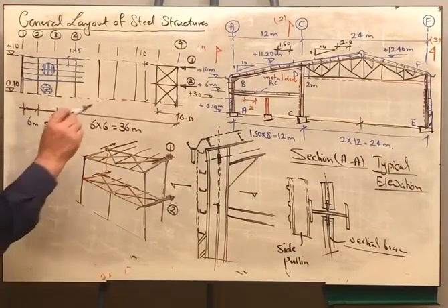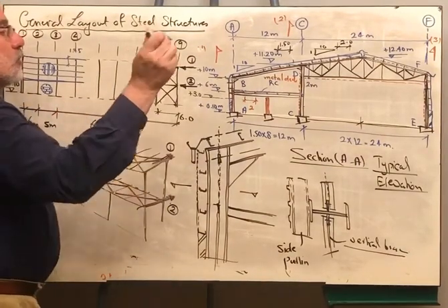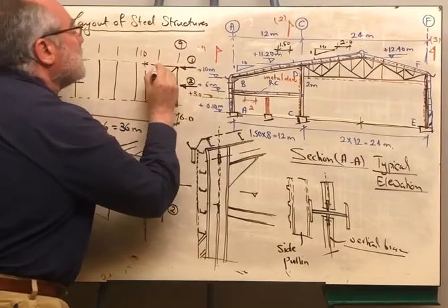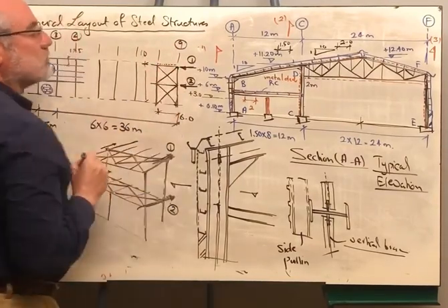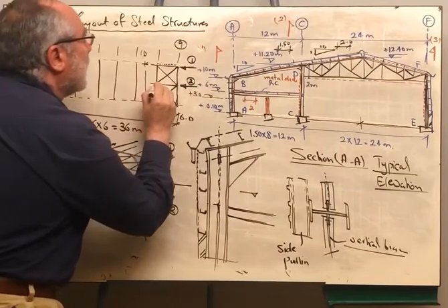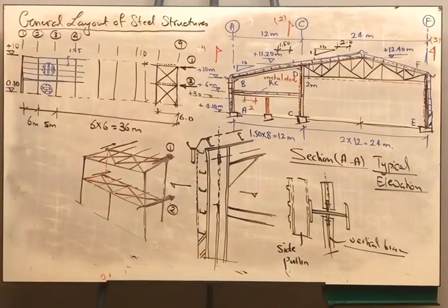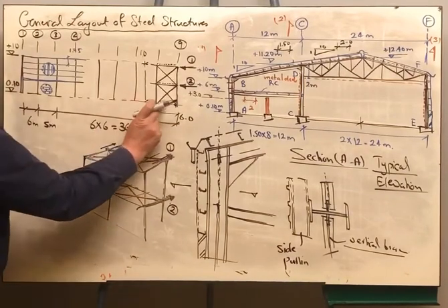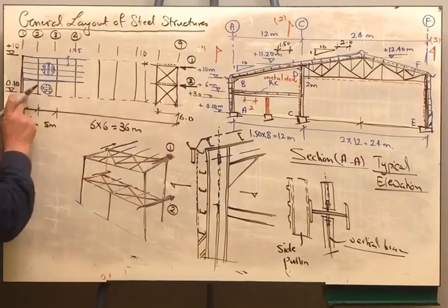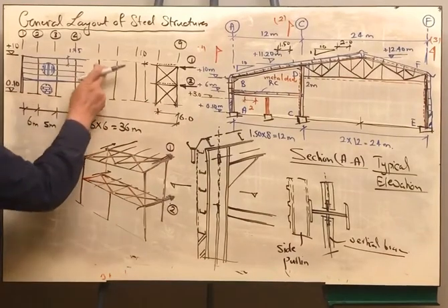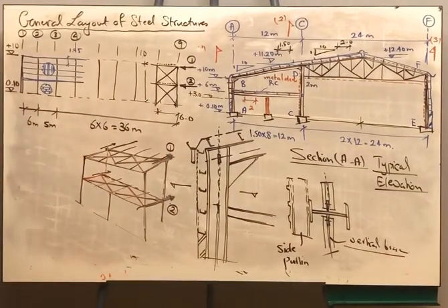One more thing, there is a bracing normal to the board. I have to indicate here the presence of the upper bracing at this level and the presence of the bracing with the mezzanine floor at that level. Is this enough? Of course, we have to have a bracing in the beginning and a bracing at the end and in the middle, as we drew before in our lectures.